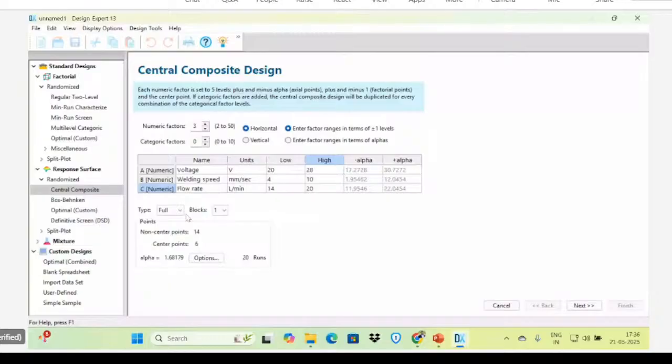And if we are having limited raw materials or limited control over this, we can go for a small or partial factorial design also. But by considering full factorial design, the optimum process parameter is good, because it is considering all the possible intensive factor combinations. The software is ultimately determining which process parameter combination is the best to get the best output. So full factorial design, I will suggest you to make it.